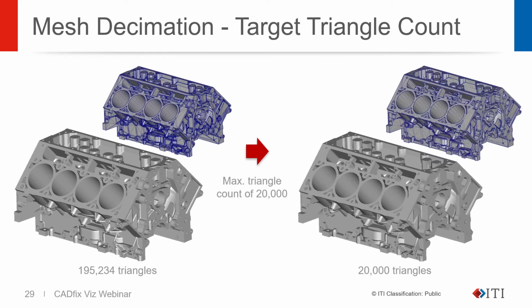This is an excessively complex mesh on the left. It doesn't need to be that nice. Obviously, with that number of triangles, we have nicer shading of the model, and you can see that between the one on the left and the one on the right. But for our purposes, we need to reduce that triangle count, and this is a really good way of doing so.